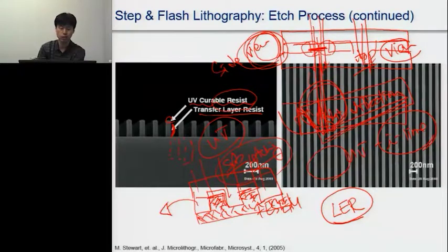In other words, the patterns on the resist simply mimic the pattern on the master mold. So even though we are using the same UV wavelengths for UV nano imprinting lithography, we don't have this light diffraction issue.